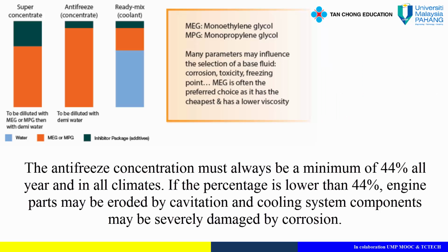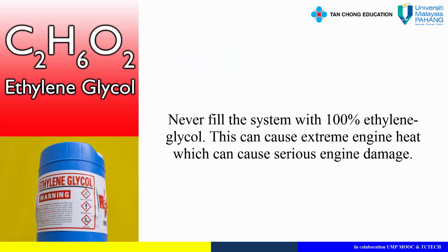The antifreeze concentration must always be a minimum of 44%, all year, and in all climates. If the percentage is lower than 44%, engine parts may be eroded by cavitation, and cooling system components may be severely damaged by corrosion. Never fill the system with 100% ethylene glycol.